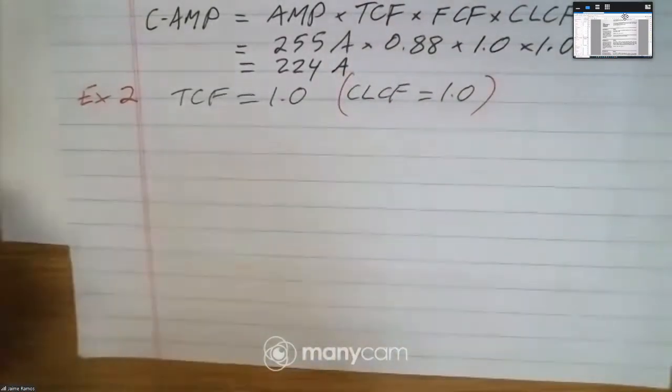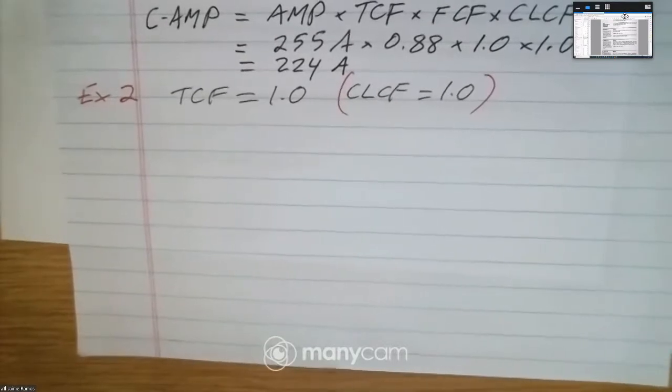Dr. Ramos, the fluorescent lighting introduces harmonics, right? Yes. Fluorescent lighting introduces harmonics, yes, because of the electronic ballast and also because of the discharge characteristic. No, it's more on the magnetic core of the ballast, because they have a series ballast with the lighting, and that ballast has a magnetic core, and magnetic cores introduce harmonics.